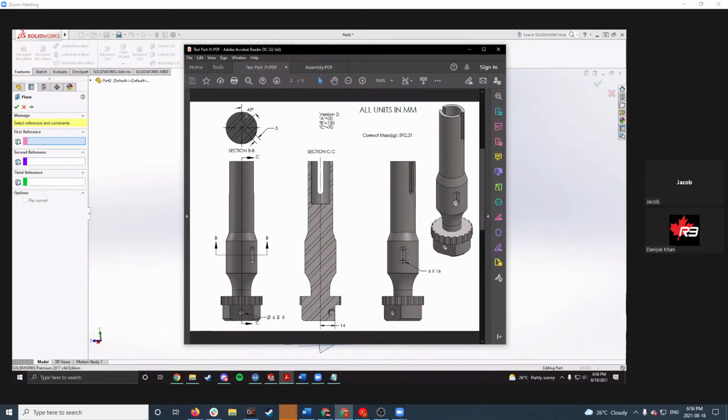Either way, this is a little confusing, because I think the view is above, but if you look at the section arrows, they're pointing upwards, which means it would be like you're looking at it from below. So you're looking in the direction of the arrows. So then this is correct in this orientation, this is where the cut is. And it's on the front side,